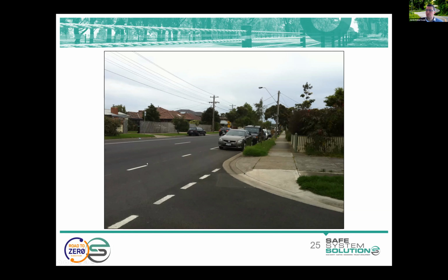If you're referring to this continuity line here, we would want to provide about 1.5 meters space for cyclists through there, if that's where you're coming from, which would mean that our build out wouldn't be very large at all. It'd be sort of 1 meter ish.